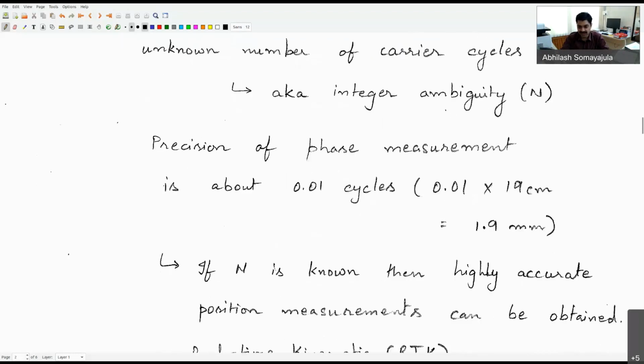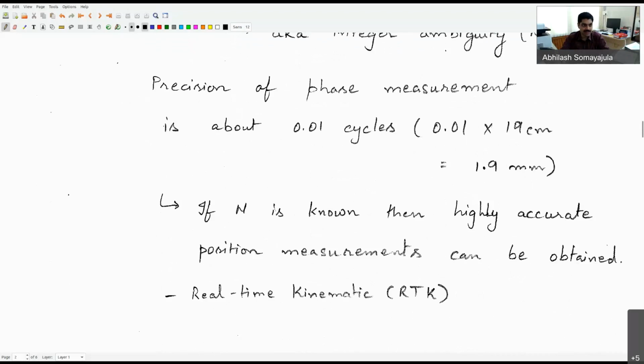So whenever you're looking at what are called real-time kinematic or RTK systems, that is what is happening behind the scenes. You're looking at not only how much is the difference between a known base station and its measurement, but you're also looking at what is the phase difference in my receivers. And you're using that phase information in order to correct your measurement to come within a much tighter error bound.